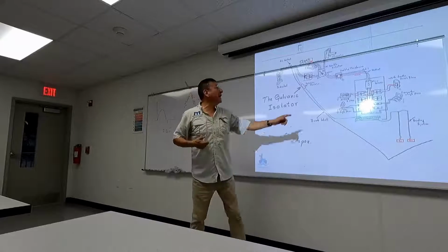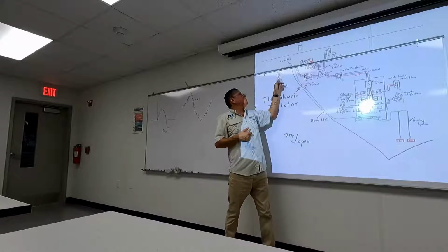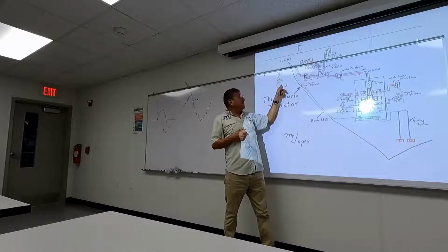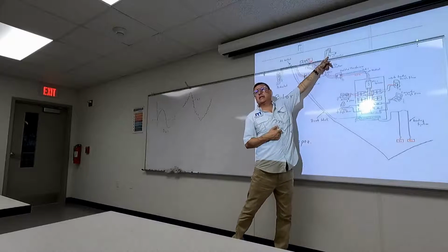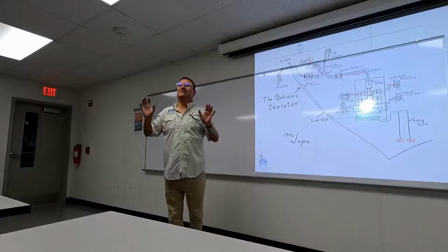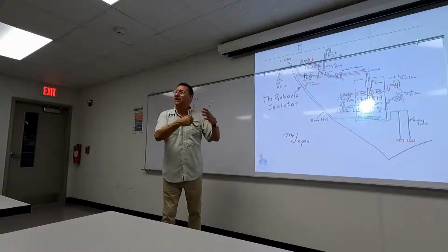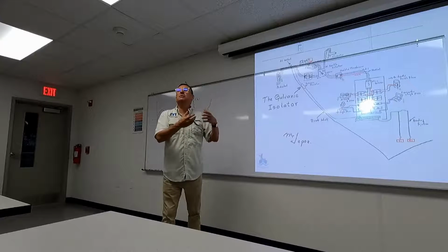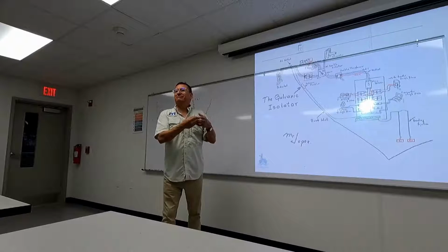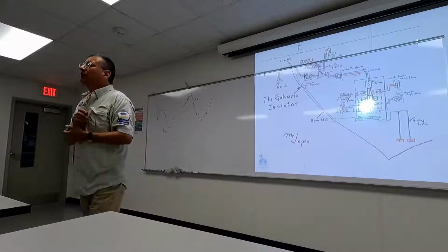You understand why I recommend here, not here? Because with this you only clean that one. But what happens if I have an old generator? The old generator produces contaminated signals. If the winding, you remember the winding yesterday in the rotor and in the stator? If you have too much humidity, dirt, the signal is contaminated.